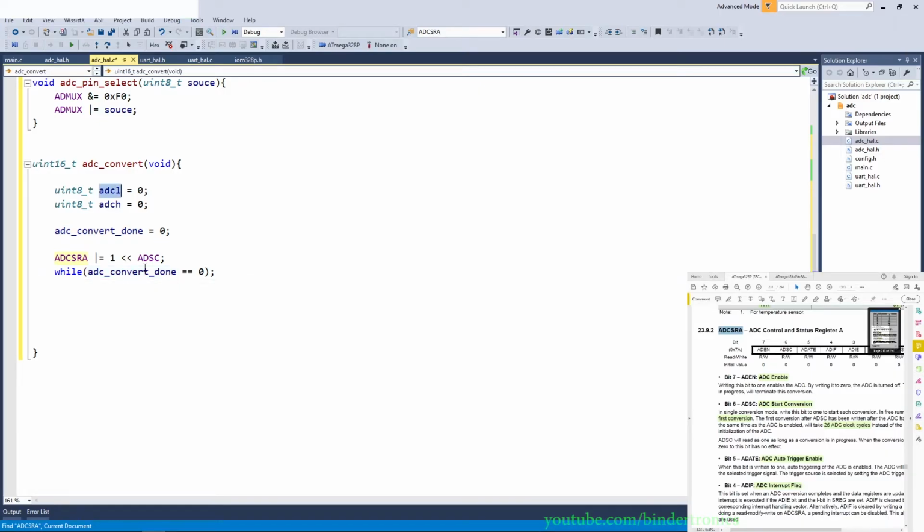And then we are going to see something that looks wrong, but it's actually correct. We take our ADC convert register, Control Shift U, that uppercases it, so it gives us the register. Then we take our high dummy value and we copy that, and then we also Control Shift U it for uppercase, and then we return ADCH left shifted by 8 and ORed with ADCL. Now someone will tell me in the comments, you can just put in these 2 registers right here. Guess what? Somehow in the optimization, it doesn't read the high register, and then you just continuously get the same value. It reads once and doesn't read ever again if you don't do this terribleness.